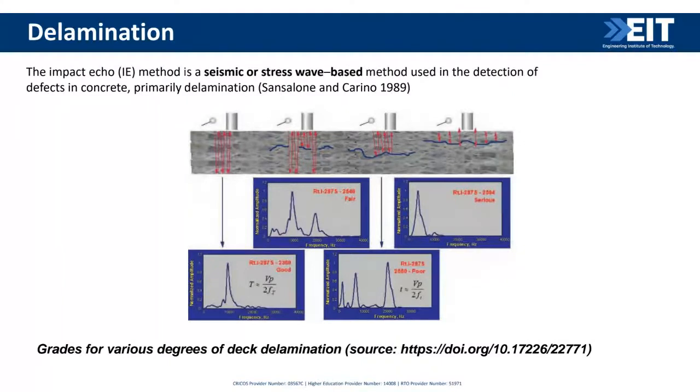And here I just share at least one example of each in relation to the type of deterioration. We have some micro cracking sometimes in our structural elements due to several causes: alkali silica reaction, ettringite formation, plastic shrinkage, freeze-thaw cycles. They can start at a micro level, but over time cracks progress and grow, and crack propagation, we know, is one of the main challenges we face as structural engineers.